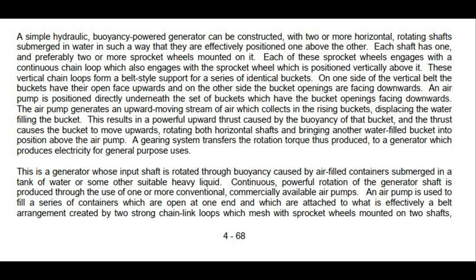On one side of the vertical belt the buckets have their open face upwards, and on the other side the bucket openings are facing downwards. An air pump is positioned directly underneath the set of buckets which have the bucket openings facing downwards. The air pump generates an upward moving stream of air which collects in the rising buckets, displacing the water, filling the bucket.